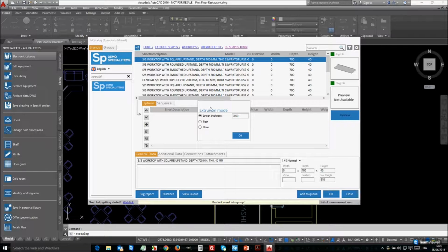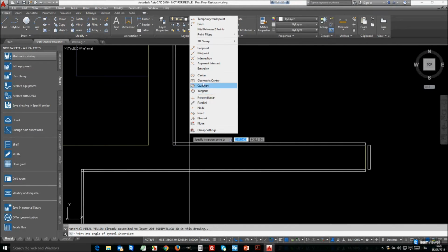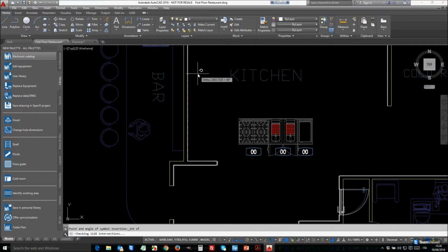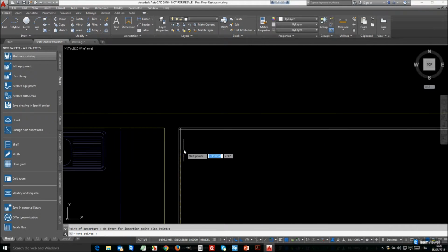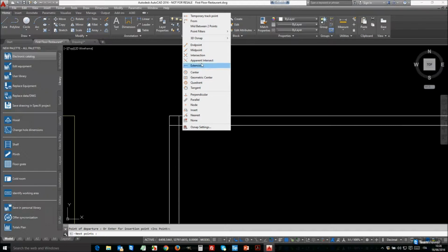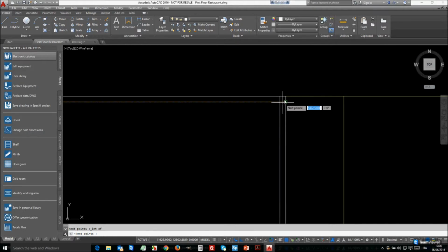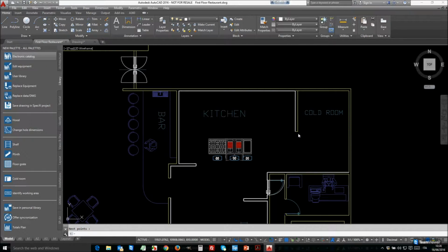You can select the shape. This is a worktop, okay, and I can insert at 810 millimeters because I have to consider also the height of the worktop, and I can insert it. I can choose the extrusion mode because this is extrude shape profile, and I can choose if I want to extrude it in linear way or following a path or a draw. Supposing you want to follow a wall, you can choose draw, and you can select, for example, starting point, intersection. You give the angle, so you can choose the rotation angle, and then you can select and follow exactly the walls.